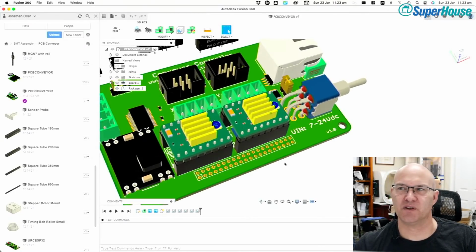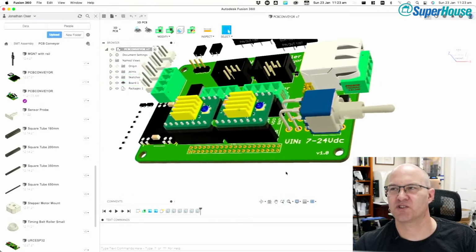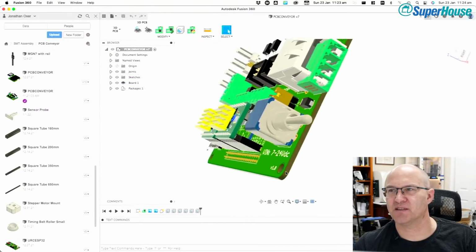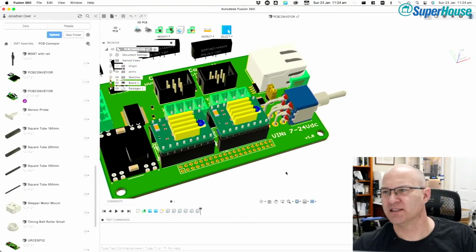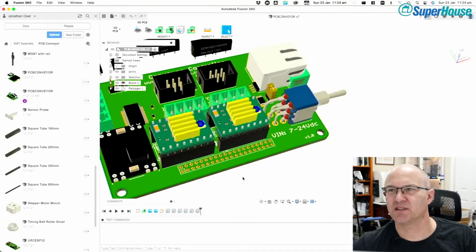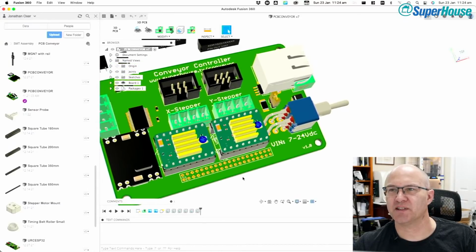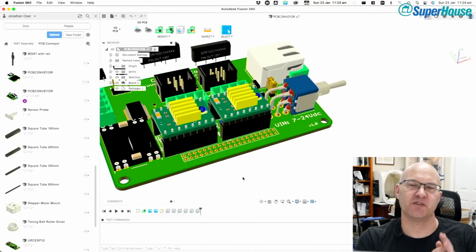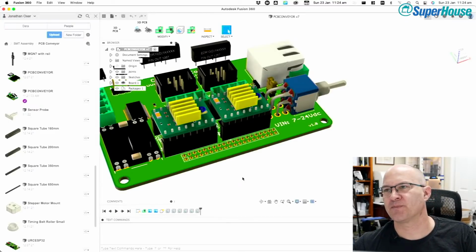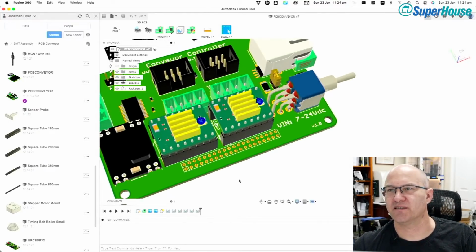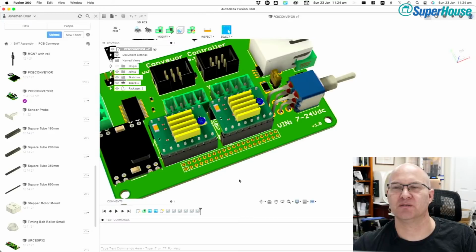And these stepper driver modules are only a few dollars each. They are shockingly cheap, and they come in a whole lot of different varieties. So you can get one that has the particular characteristics that you want, depending on what steppers you're going to be driving. In my case, I'm going to be driving tiny little NEMA 8 steppers that take very little power and aren't really going to stress this system at all.